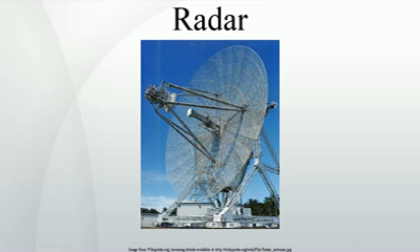Polarization. In all electromagnetic radiation, the electric field is perpendicular to the direction of propagation, and this direction of the electric field is the polarization of the wave. In the transmitted radar signal, the polarization can be controlled for different effects. Radars use horizontal, vertical, linear and circular polarization to detect different types of reflections.